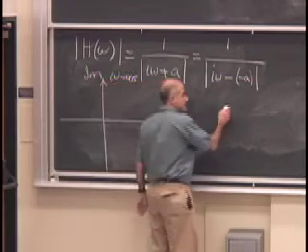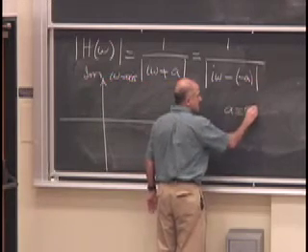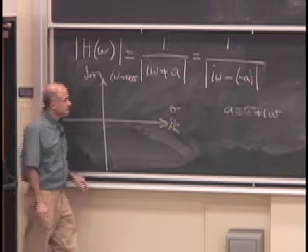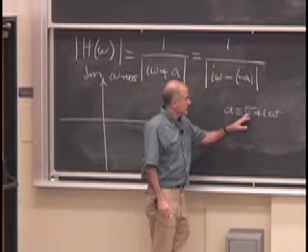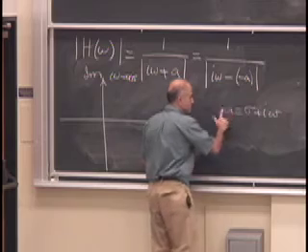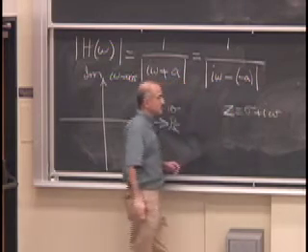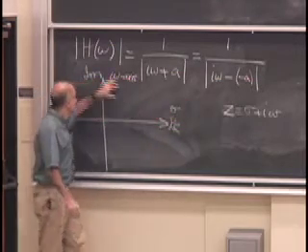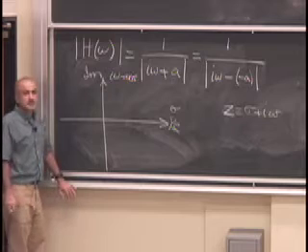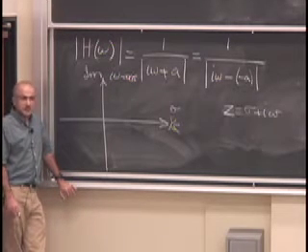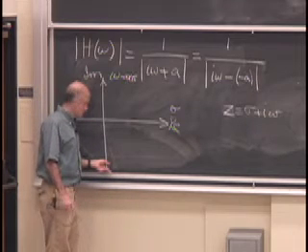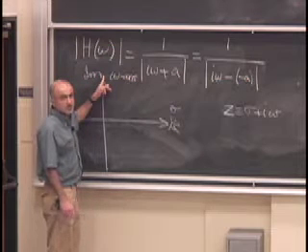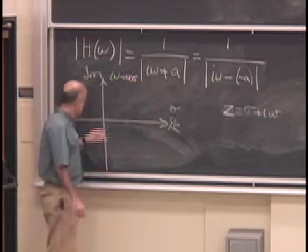So any number, in this case Z, a complex number, has a real part and an imaginary part. So the real axis is sometimes called the sigma axis, and the imaginary axis is called the i omega axis. For continuous time LTI filters, we measure the frequency response by walking along from minus i infinity to plus i infinity. It's not the unit circle that we worry about. So this is where we go along.